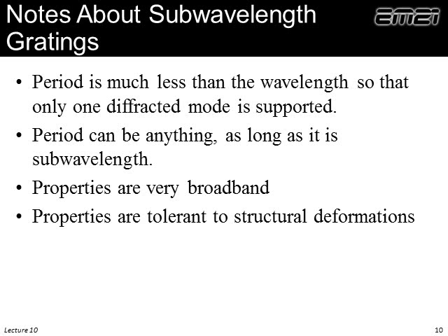They will work the same from DC up to their cutoff. And what the cutoff is, is when the wavelength starts approaching the period of the grating and it becomes non-subwavelength. So they're very, very broadband, and that's unlike diffraction gratings. And also these subwavelength gratings, in my experience, are very tolerant to structural deformations as long as those structural deformations are random in nature. They can tolerate those pretty well.